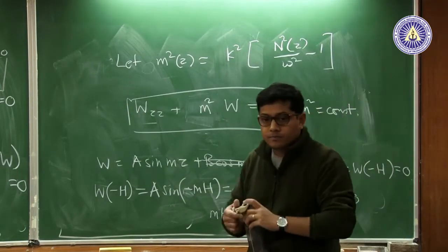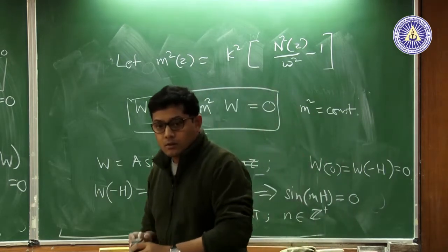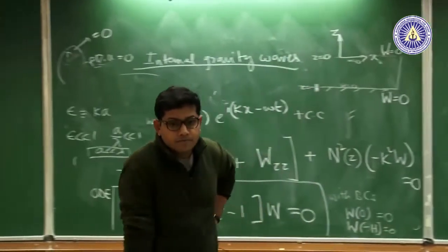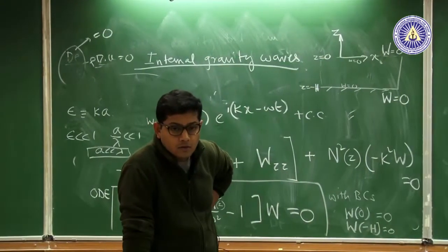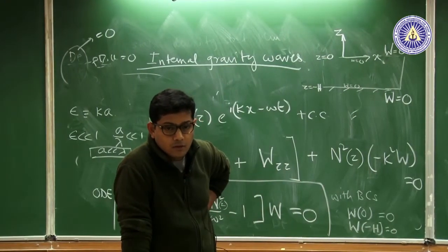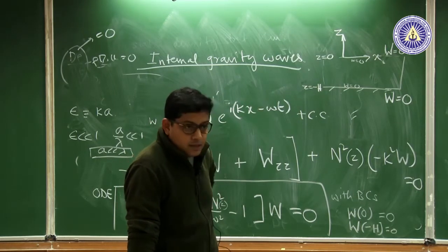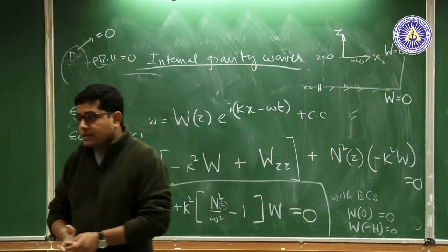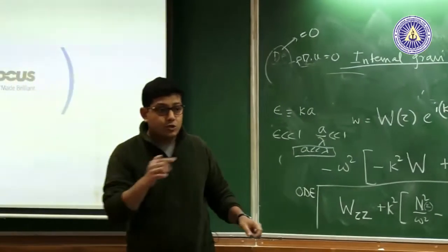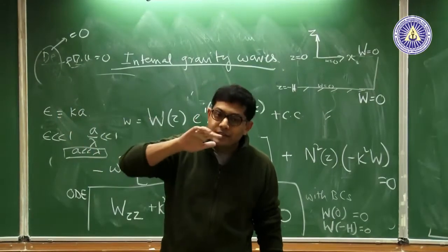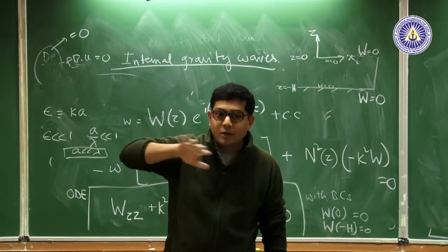Can I just add one thing? The frequency of the internal wave that we are talking about here is very much less than the frequency of the free surface wave. And that is really the justification of the rigid lid approach. Yes, the free surface waves obviously travel fast. The video which I showed is one where the free surface also travels because of this.